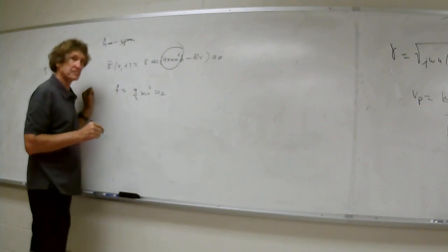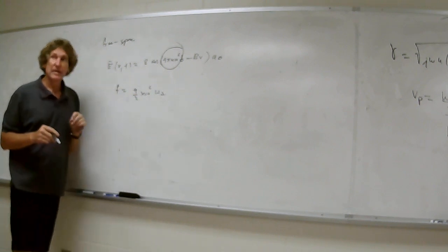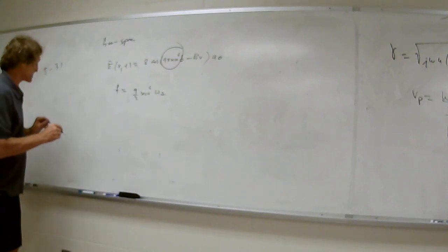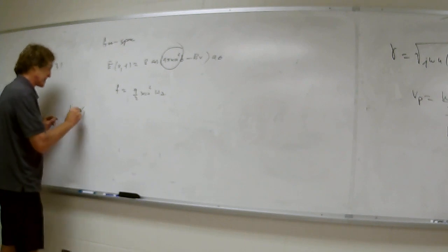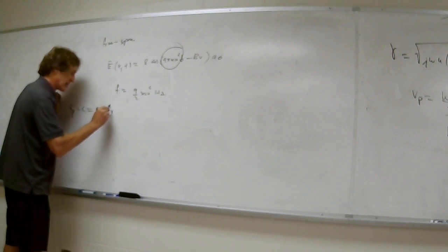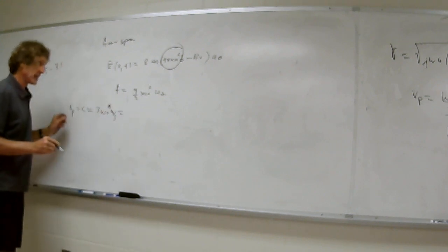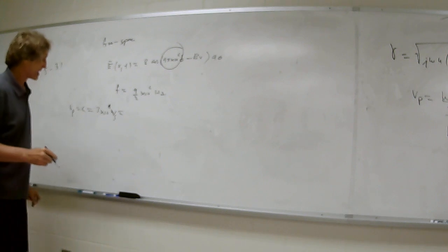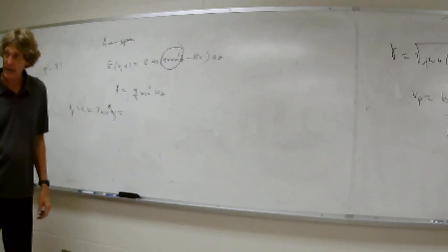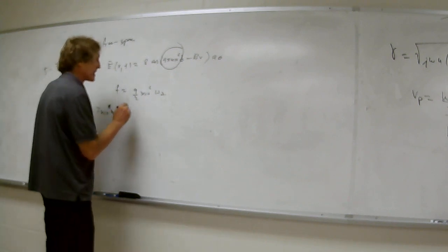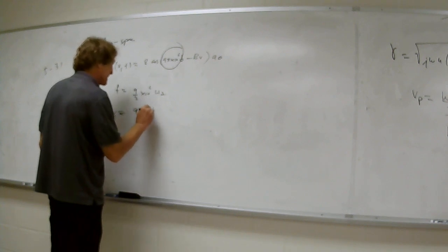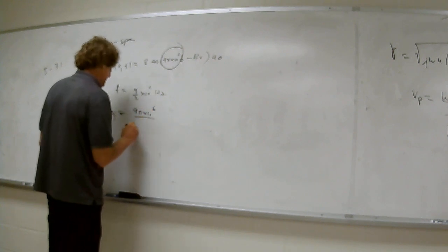What's the next thing he wants? It's free space, right? Guys, be attentive here. What is the velocity in free space? C. Every engineer should know this: 3 times 10 to the 8 meters per second. Regardless of what it is, it's omega over beta, correct, class? Yep. So we have omega. Omega is equal to 9 pi times 10 to the 6, and it's over beta.